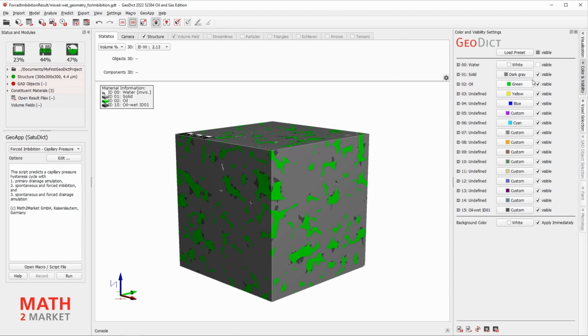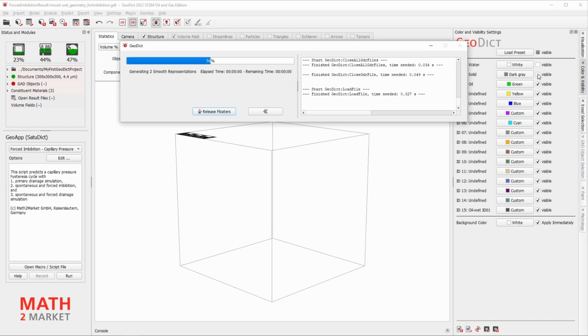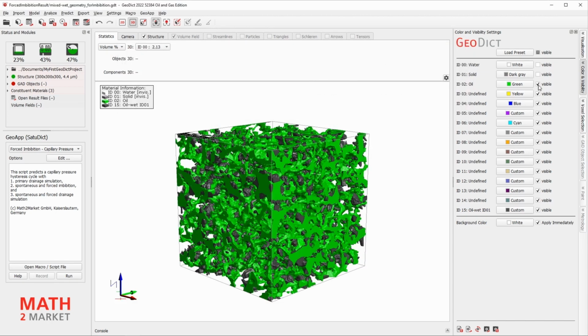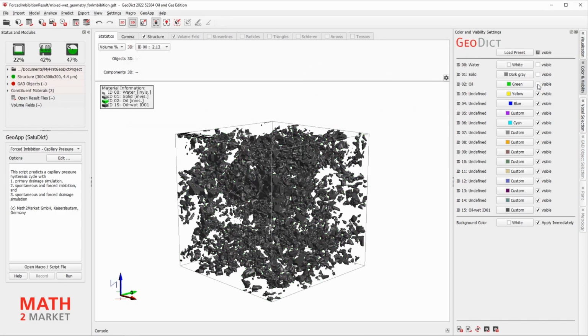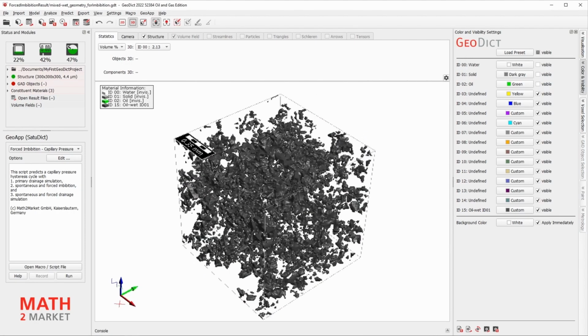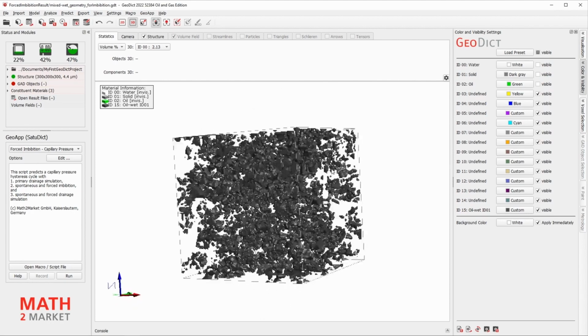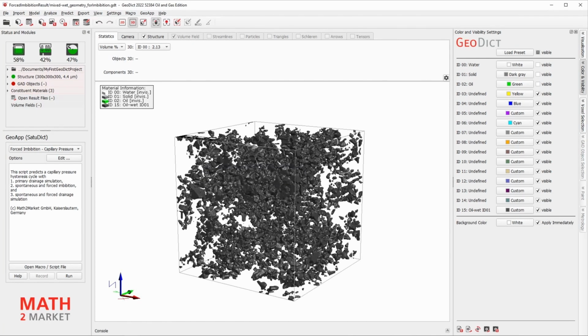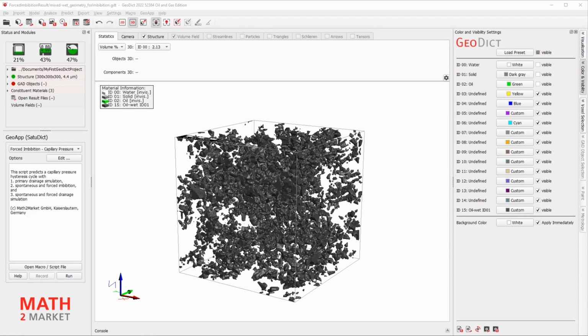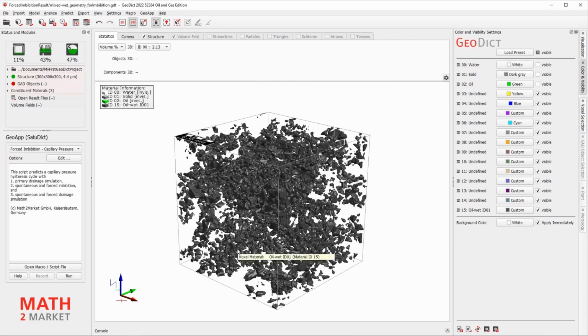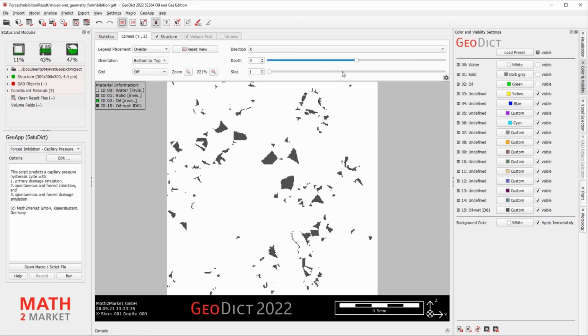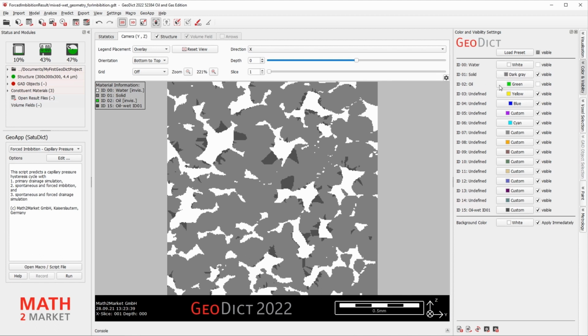You can now uncheck the visibility of your structure, of your oil, to have the mixed wettability visualized in GeoDict. In this case, we've only visualized the oil-wet surfaces. Have a look at them in 2D. And check the visibility box for the quartz grains.